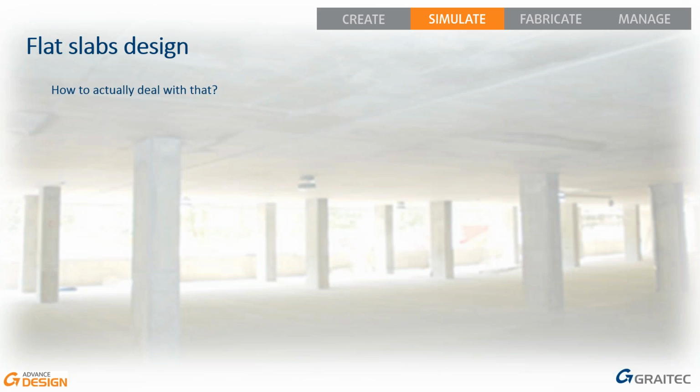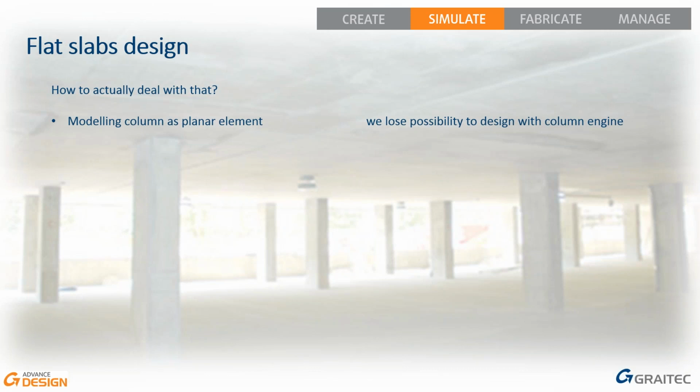So how to actually deal with that? What could we do to get the result as I showed in the previous slide? You could actually model your column as a planar element, but you will lose the possibility to design your column with the column engine, so you can only design this as a wall. So it's not what we want. We will actually spend more time designing rather than saving our time.